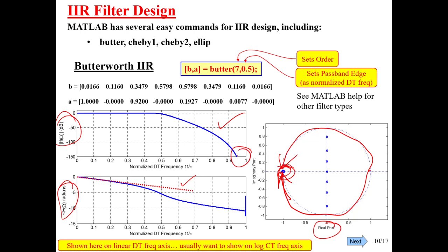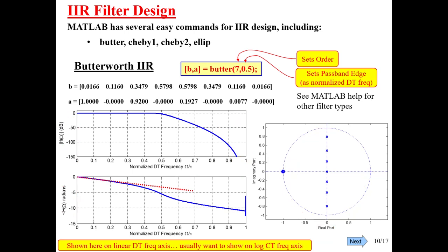So that's what's making this go down to 0 in non-dB and minus infinity in dB. And then this is interesting. It's like a wall of poles on the imaginary axis. And that's a characteristic of discrete time Butterworth filters. Later in an upcoming video, we'll see the structure for continuous time Butterworth filters.